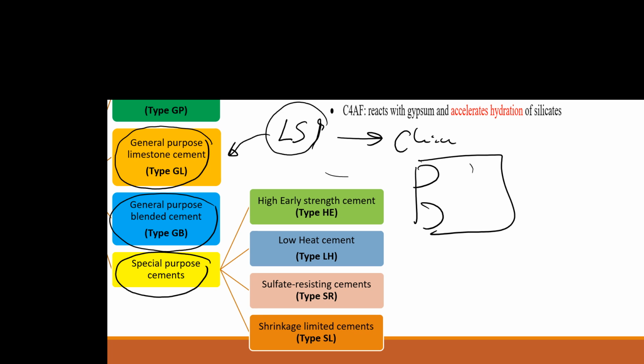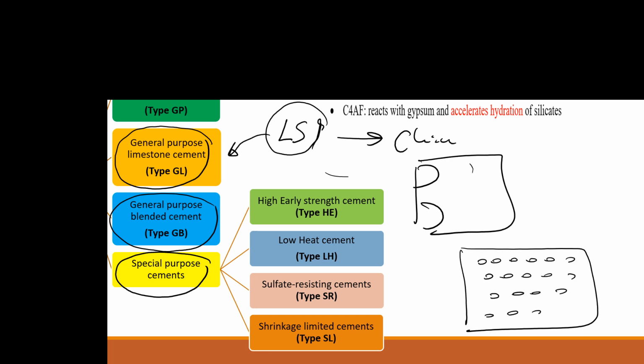But sometimes we have to purposely add air. Purposely adding this air, we call air entrainment. This air is evenly distributed throughout the concrete. Purposely adding air in the concrete weakens the strength, but sometimes we need to do that to get rid of other issues. So in what kind of situations do we need to do this?